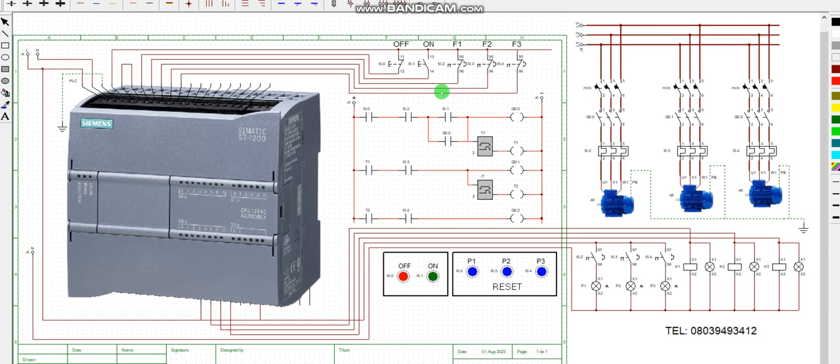Okay, so this other logic here, this section of the logic, they are my output bits. Output bit 1, 2, 3. They are output bits belonging to this contactor, right? They are closing this contactor. Then the whole of this, they are all my input bits representing this as well. So part of this is what I just generated here so that I can start from the control room, and also reset the fault from the control room.